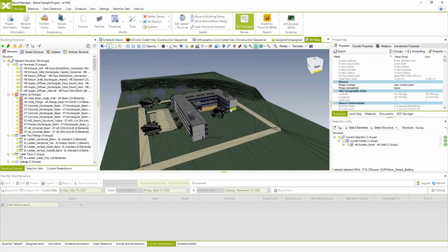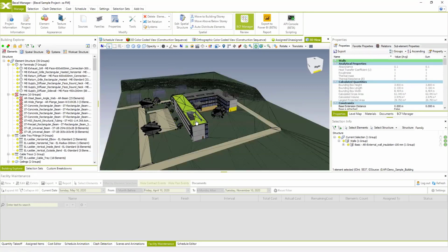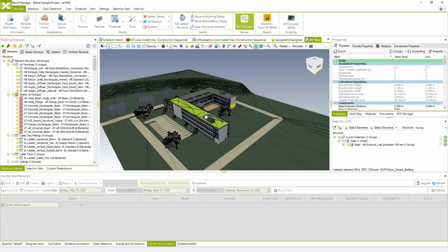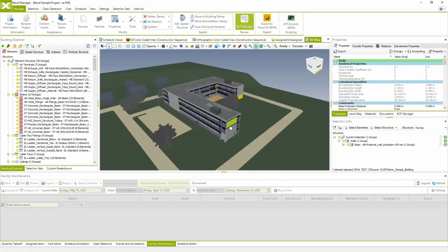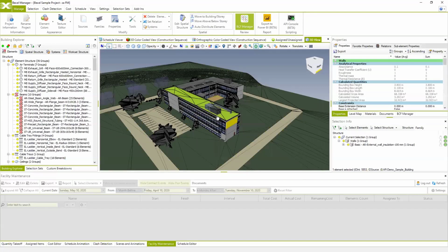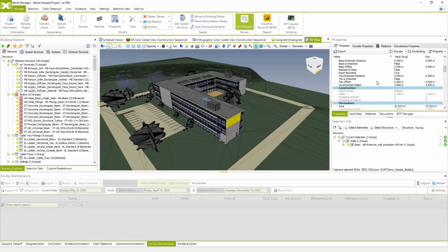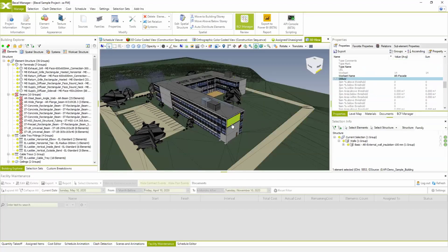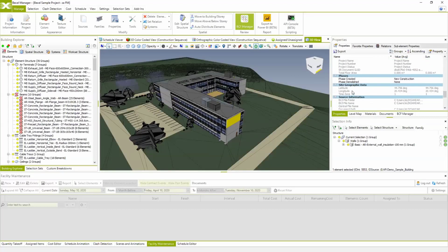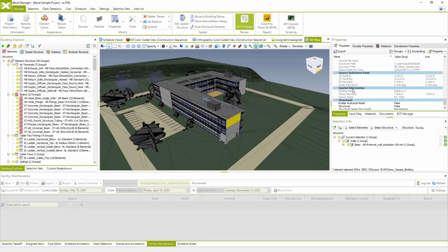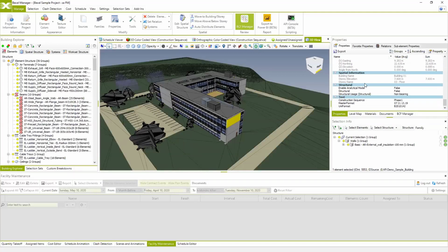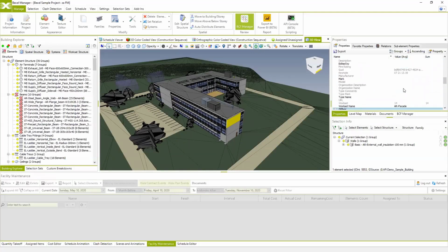you the information about all these elements and the BIM model information which are stored for each BIM model element. So by clicking each element from your project, you can access the information of that specific element. And of course, if you input the information which is related to specific requirements regarding facility maintenance, all this information can be accessed and stored right here. And they can be accessed or stored within specific groups of the properties.